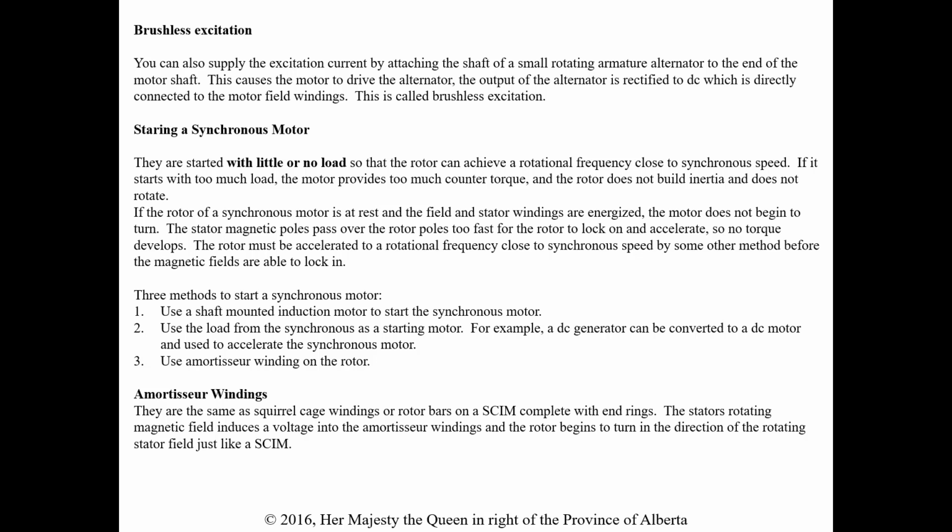Starting a synchronous motor. This is where the synchronous motor has some trouble. We want to start it with little or no load so that the rotor can achieve a rotational frequency close to the synchronous speed. If it starts with too much load, the motor provides too much counter torque, and we cannot get enough inertia to get it to start to spin. If the motor is at rest and the field and stator windings are energized, it does not begin to turn. The stator magnetic poles pass over the rotor poles too fast for the rotor to lock on and accelerate, so no torque develops.